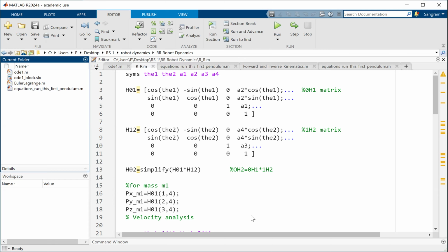Right now, you are deriving the differential equations of motion purely based on the scalar quantities, which means you don't have to draw the free body diagram. You don't have to worry about how those joints are connected. If you want to solve this two pendulum problem using the Newtonian approach, we can solve it, but it will take at least 2 pages to solve.